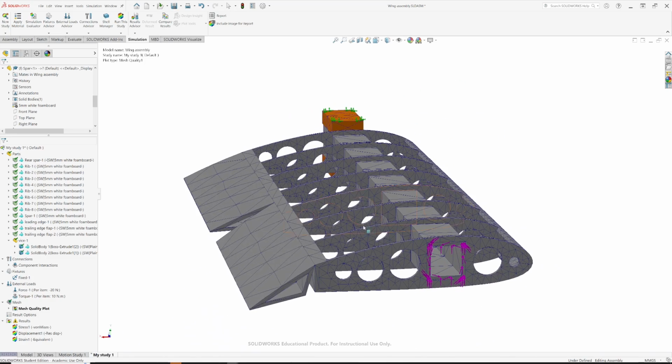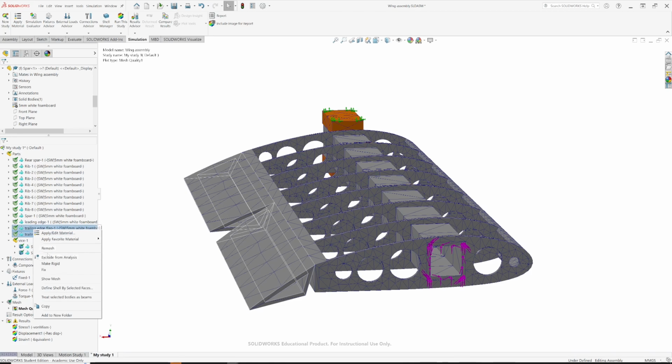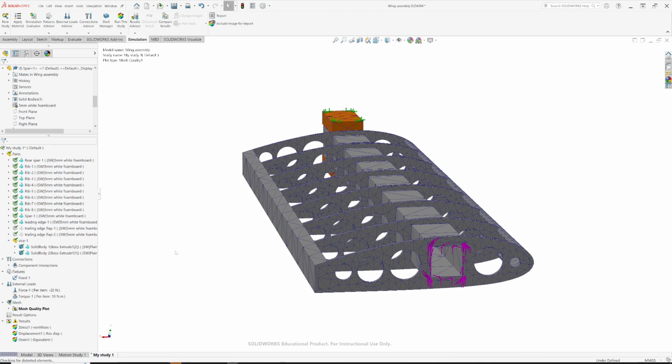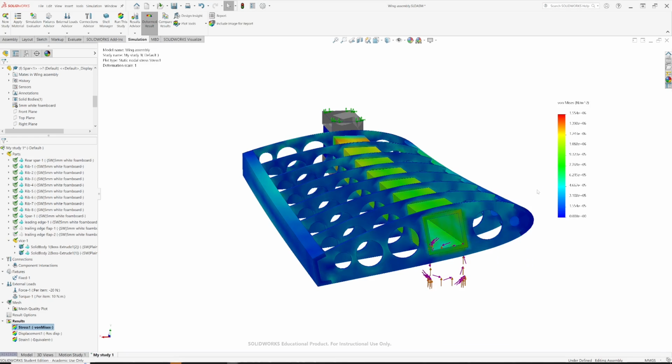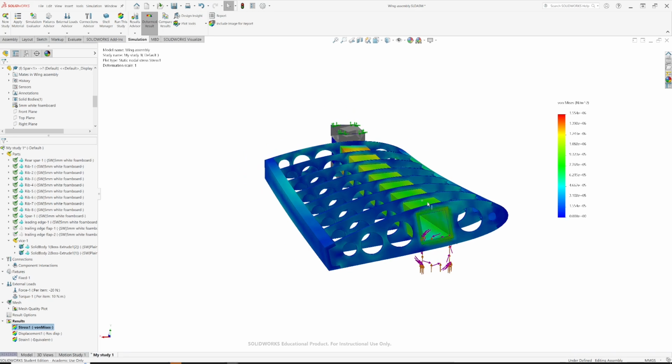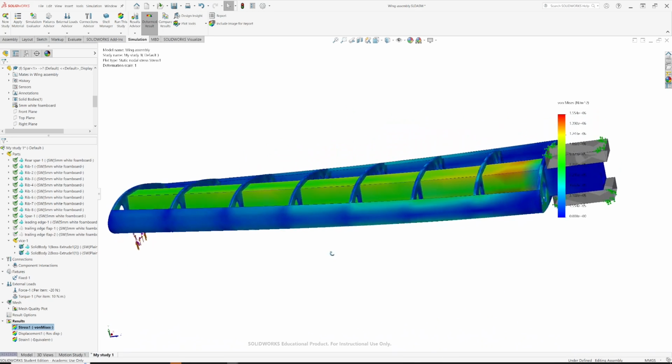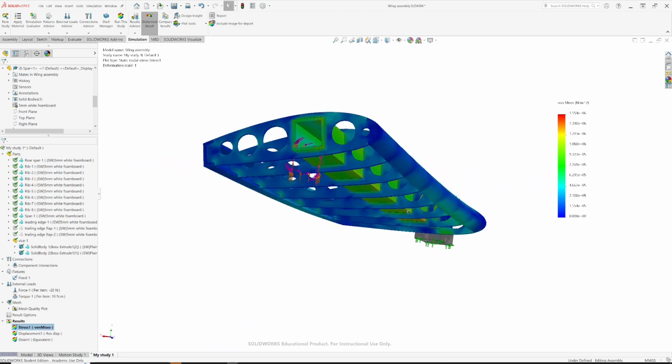While we're doing this, these control surfaces are not constrained because they're on hinges, so it actually makes no sense applying loads to these. So what I'm going to do actually is remove these, because it doesn't make any sense to include these. Okay, so we're applying a force and a torque. Those are all the same, so it's remembered that. You can still see those on there. Okay, let's give it a try. So no. And there we go. We've got a wing that is bending and twisting under load.